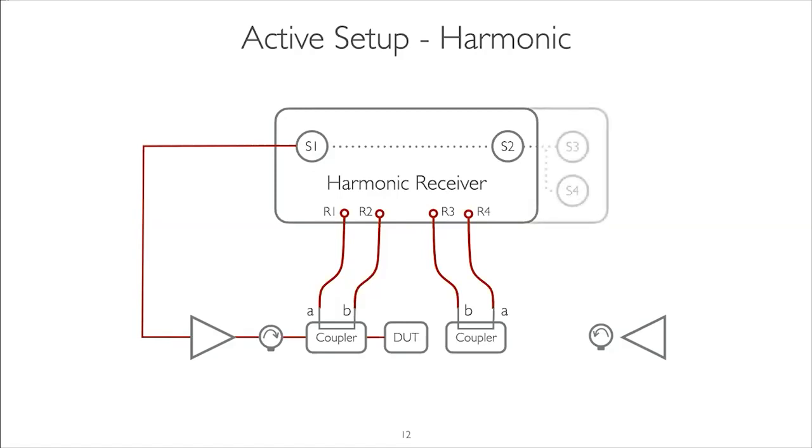But now what we're going to do is, again, all the signals that we're injecting to the device need to be an active signal. So it needs to be a signal generator that's fed through an amplifier to the device. So initially we only had the fundamental one, so let's just move that one aside. So that's our fundamental amplifier driving the fundamental signal. Usually that's the biggest one because that's the most significant signal that we're controlling. But now if you want to add a second signal for a second harmonic, well, you have a second amplifier with an isolator, and the same for the third.